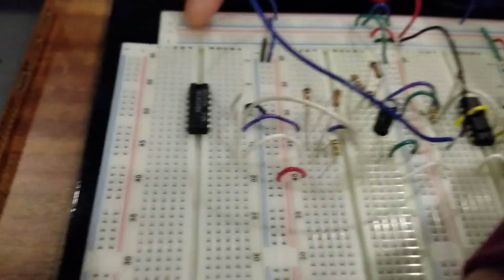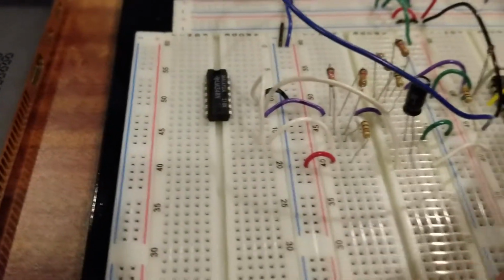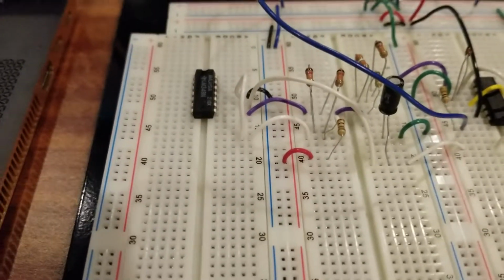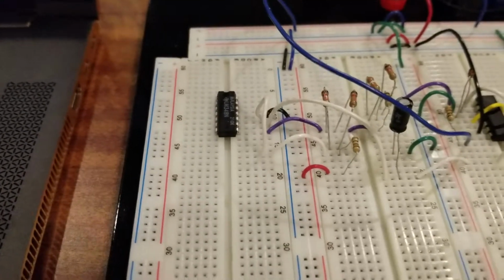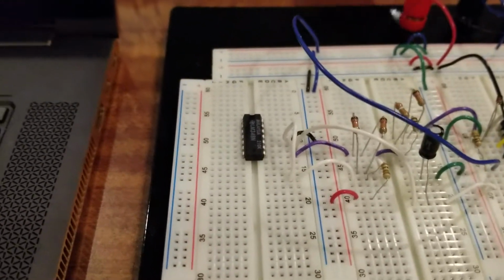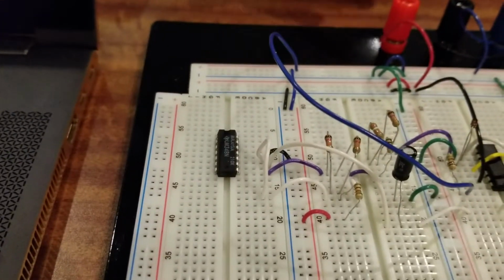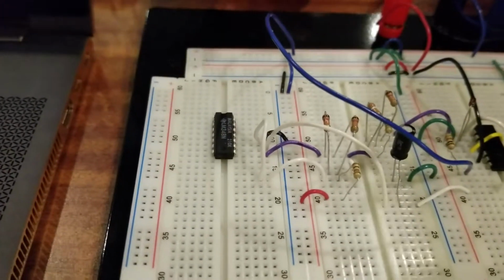All right, so this side of our circuit is the subcircuit for part B, the Schmitt trigger. What a Schmitt trigger does is it outputs a maximum or minimum voltage depending on whether the input voltage has crossed both threshold voltages that the designer decides. In this instance, our reference voltages were 3 and 7 volts. The usefulness of this circuit is that it determines whether a voltage is above or below the reference voltages that you decide.